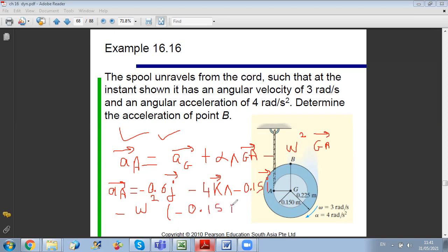So now, if you do the expansion, you have minus minus, so it's plus. K vectorial i is plus j. So you will get minus 0.6j and plus 0.6j for the vectorial product. They will cancel out. So the j component will cancel out, and you will only be left. So as you can see, you verify that the tangential acceleration is 0, and you will get just omega square 0.15 omega square along i.